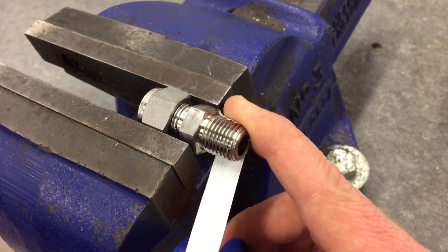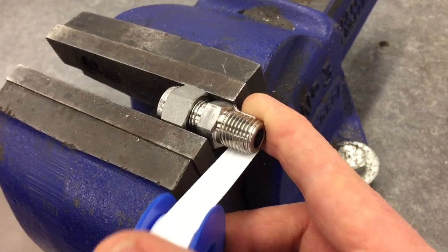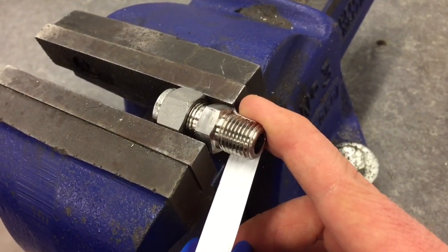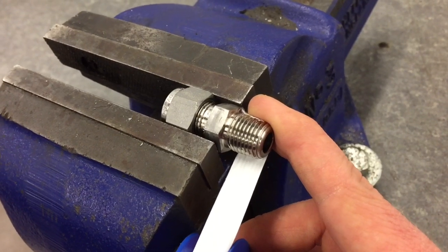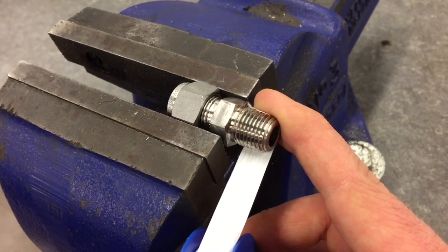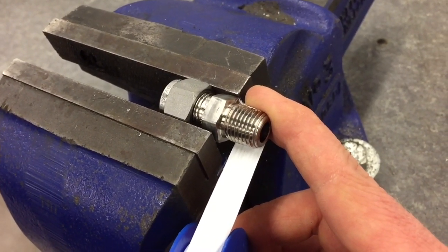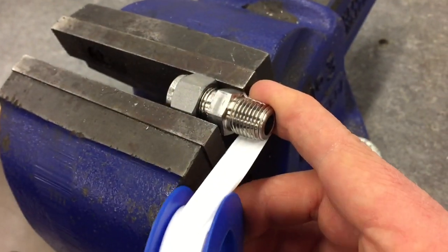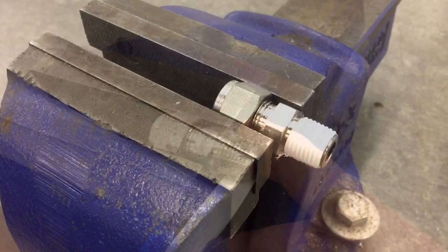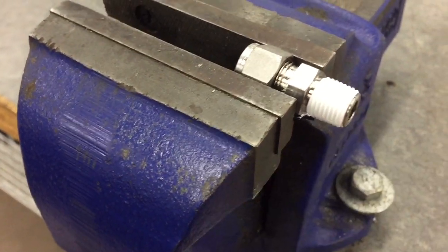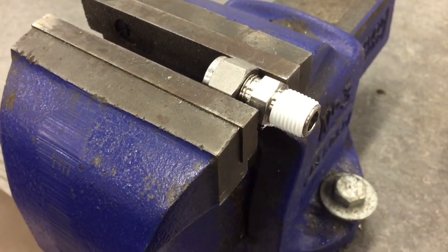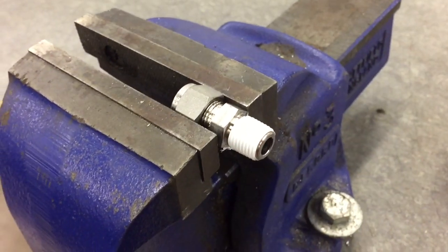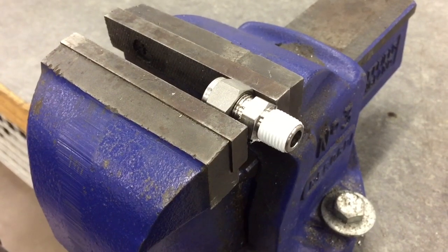It'll unwind almost. But if you tape it on clockwise, it's kind of going with the threads. It's going to be threaded on the same direction that we are going to be threading the fitting into the gauge, and it will stay on. So we want to make sure we have it taped this way, and we give it about 2 wraps. So I'll go ahead and do that. Alright, so I've taped it on, and I just had to kind of pull the Teflon tape off to break it loose. I gave it 2 wraps clockwise on the fitting, and now it's ready to be installed into the gauge.